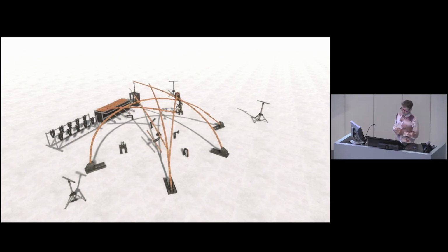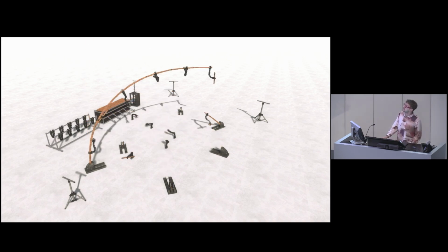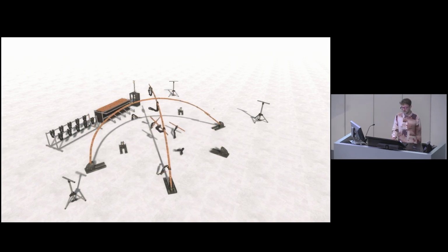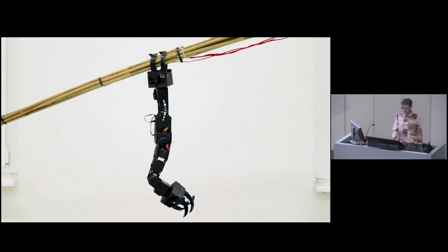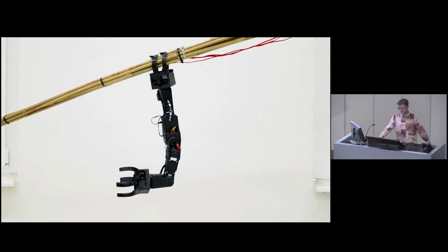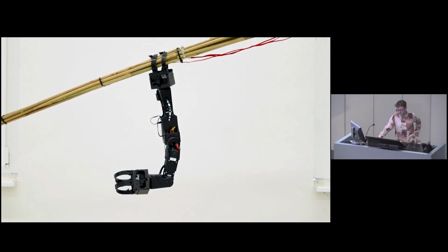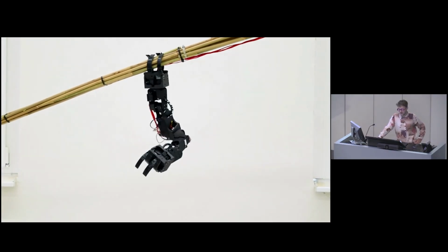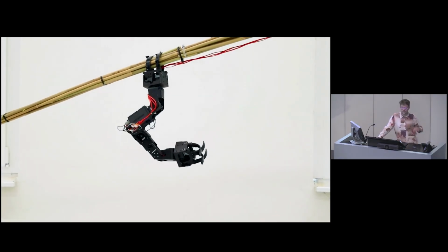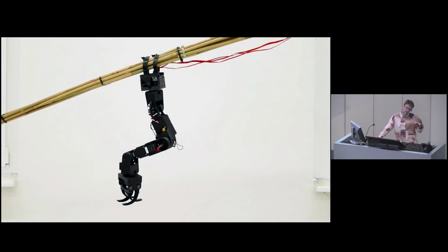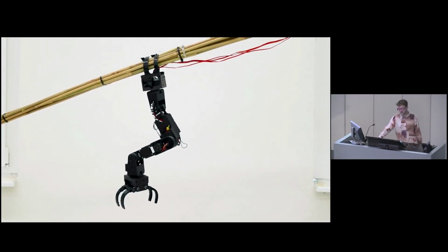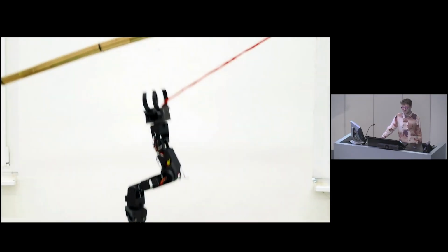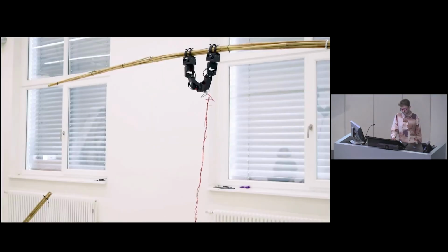The case study that was chosen was to make a structure out of bamboo bundles. The animation that you see on the side is a rough idea of how that assembly process would work. The robot has 5 degrees of freedom and a variable diameter claw gripper, which would allow it to swing on bamboo bundles, grasp bundles of different size, and navigate the structure.